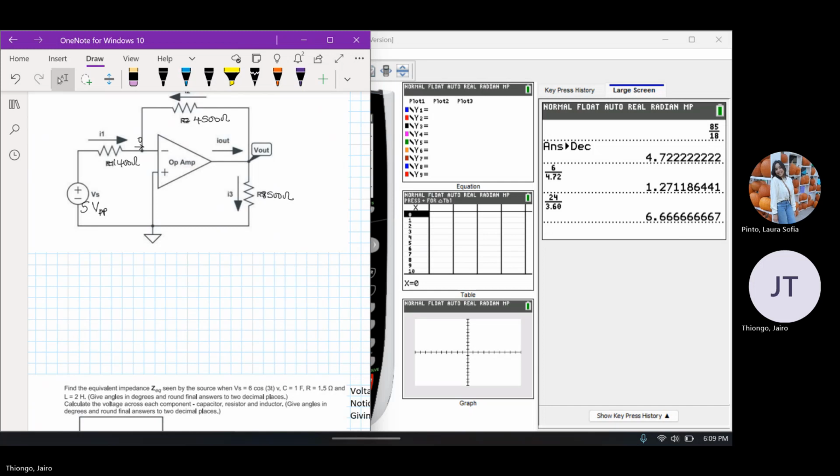One thing given by nature at this point, and in future classes we'll understand why this is the case, is that the voltage here, let's call this VA, is the same as the voltage here. That's given at the inputs of the negative and positive side. So VA equals VB. That's a rule when solving these types of problems.